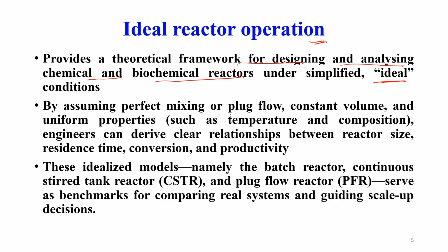By assuming perfect mixing or plug flow, constant volume, and uniform properties such as temperature, composition, density, viscosity, engineers can derive clear relationships between reactor size, volume, residence time, T, conversion, percentage conversion and percentage productivity. So, these are the important parameters for bioprocess engineering: reactor volume, residence time, conversion and productivity.